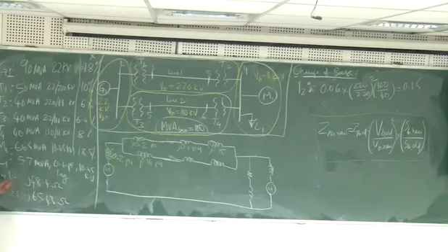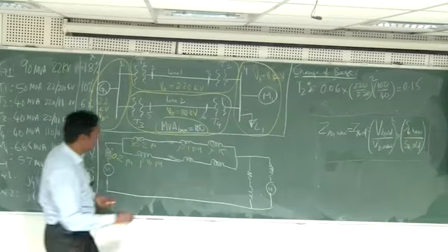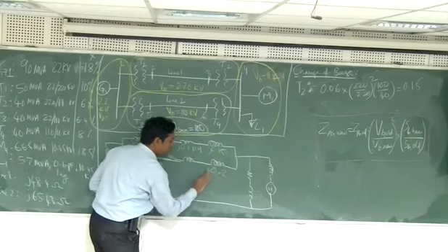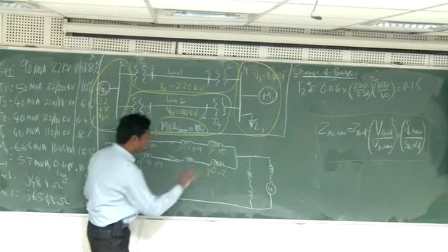What about this line? We'll come to the line later. Just finish off T4. 8 into 2.5 again, because it's the same. So 8 into 2.5 is 20, so 20%, which is 0.2. j0.2 per unit. So these are all in per unit.